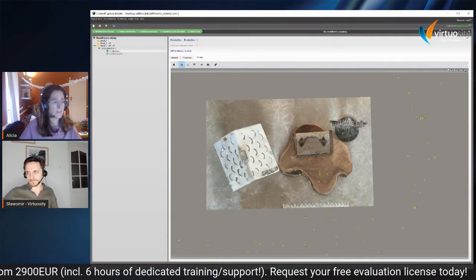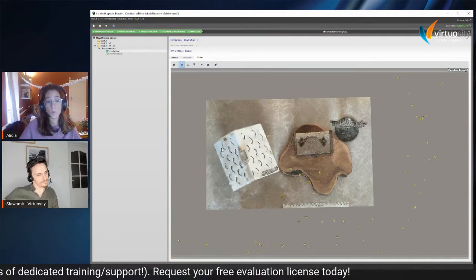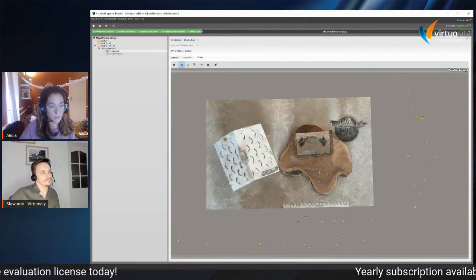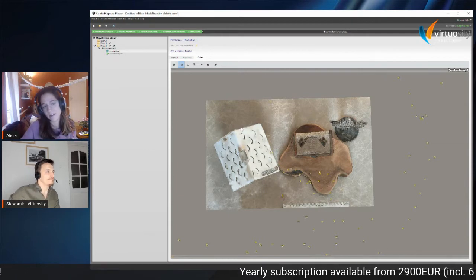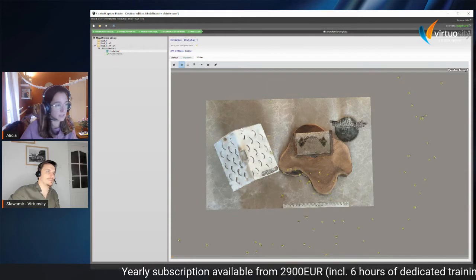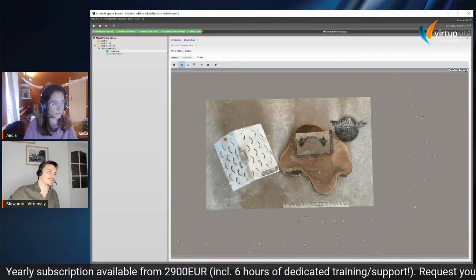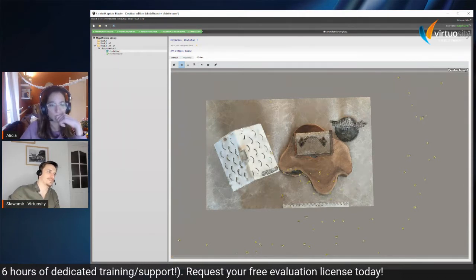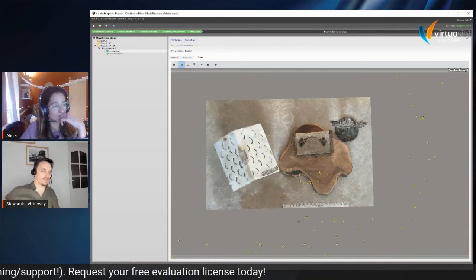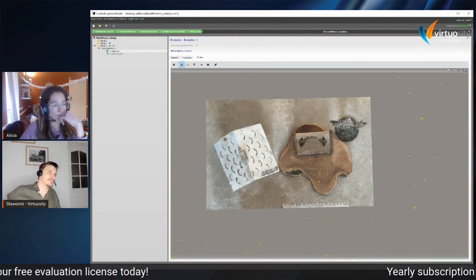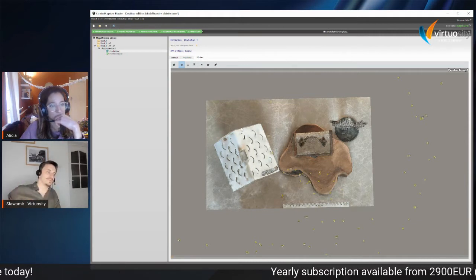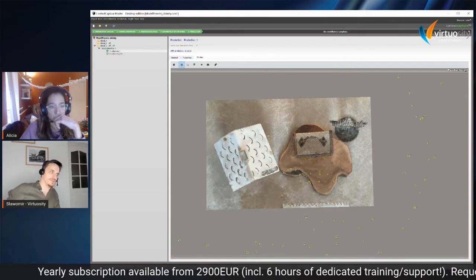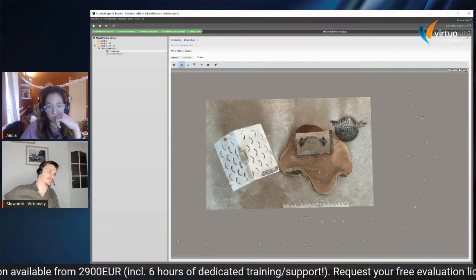Okay. Yes. So let's go back to my dog. I'm doing the 3D model of my dog. Do I need to put a scale constraint in the project, or how do I make sure the accuracy is going to be good enough? So far, if you are talking about centimeters, you can even measure the carpet after the photo acquisition and just put the scale constraint on the carpet, or on a single tile, or on any object that you know the size of in theory. In practice, you're just getting a scale and getting some metric units on the product.